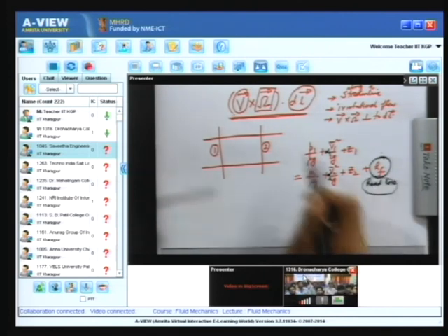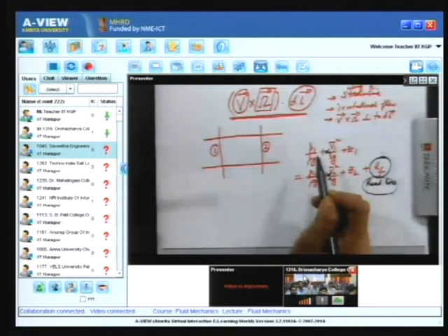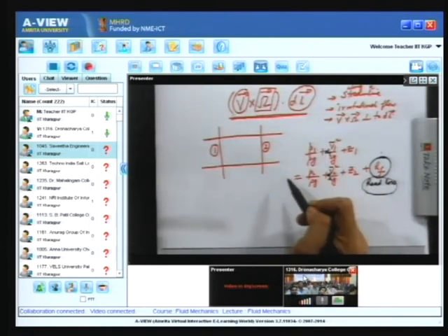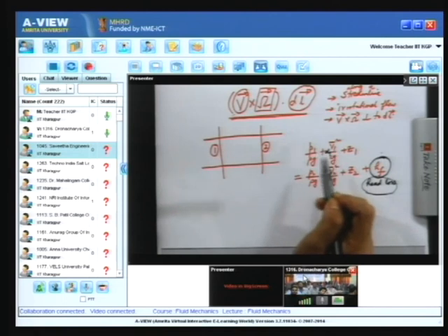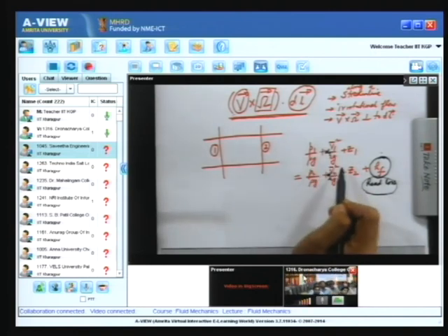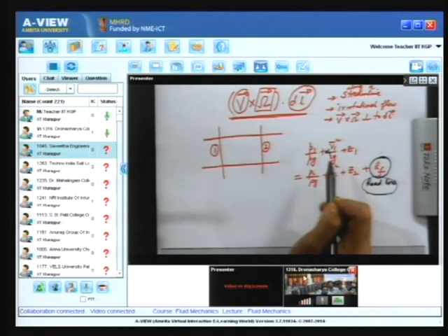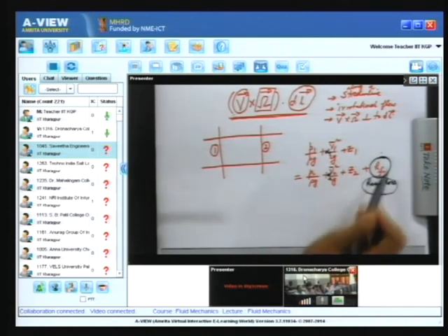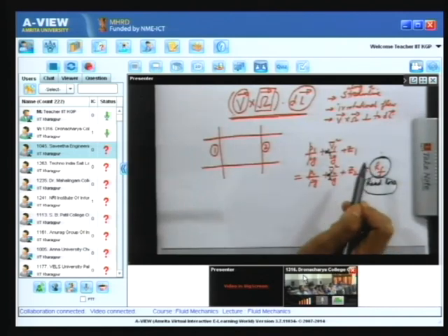So this equation, although it superficially looks like a Bernoulli's equation, and in many books it is written as modified Bernoulli's equation, has actually nothing to do with the Bernoulli's equation. It is an energy conservation equation where the heat transfer, work done, all these effects are taken into consideration, and that culminates in an equation which looks like the Bernoulli's equation, but instead of being applied across points it is applied between sections, and there is a head loss term to take into account the non-ideal effects which are not taken care of by the Bernoulli's equation.